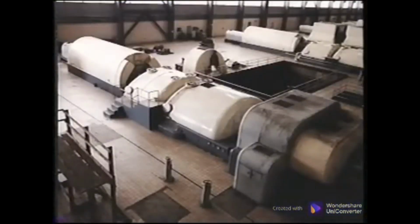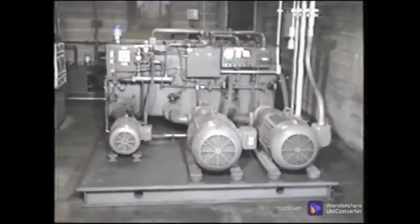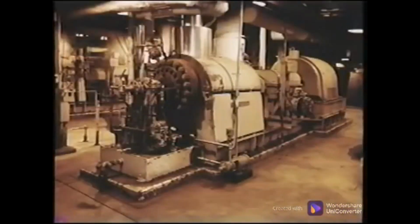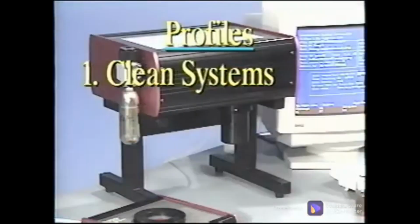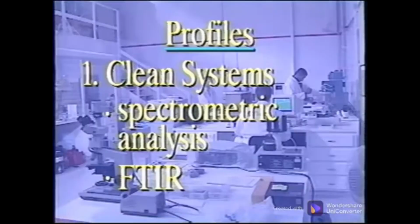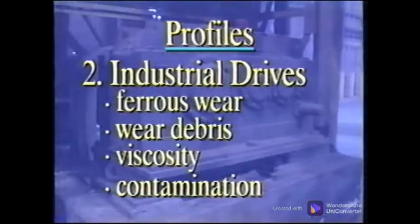One is a clean systems profile, which includes turbines, hydraulic systems, machines with sleeve bearings, and extremely critical contamination-sensitive systems. On-site analysis for clean systems should include viscosity, degradation, and particle counting. The laboratory analysis should include spectrometric analysis to test for additives, viscosity index, FTIR to test for molecular degradation and water contamination. Industrial drives such as gearboxes, crushers, chippers, and stamping processes should be tested for ferrous wear and wear debris analysis, as well as checks for viscosity, water, and other contaminants.